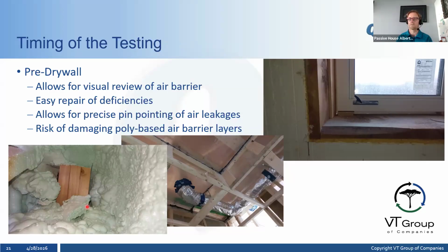So in terms of tools, there's another tool that's out there. There's a sonic camera that can visualize ultrasonic waves, and that can also be associated with air leakage. We don't have one of those. There's an argument that it may be a tool in the future that we would use, but when it comes to air leakage detection, we're trying to use whatever tools are going to give us a fast and accurate method of identifying the air leakage and the severity of the air leakage so that we can communicate to the right parties whose problem it is and how to stop it.